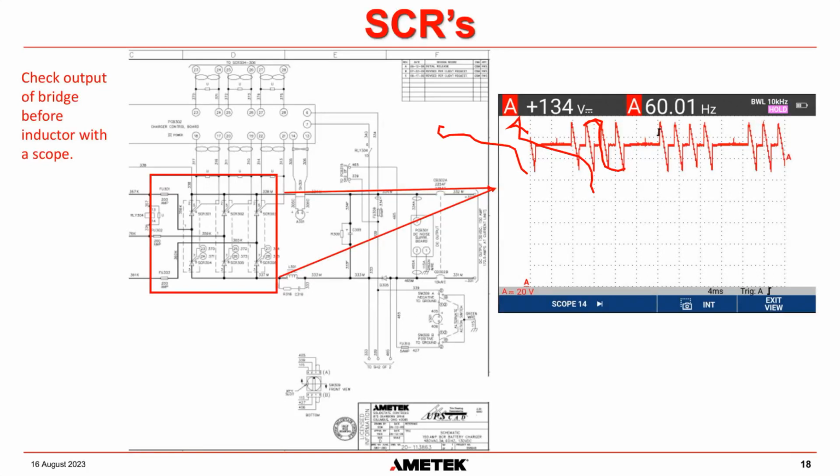And you can see the frequency. The frequency is now 60 hertz. Okay, so there is something wrong with this system. It's basically, we call it single phasing. It's that one of the SCRs or two of the SCRs are not firing.